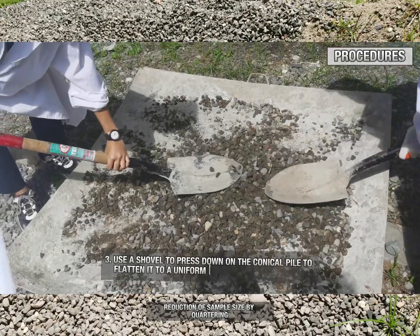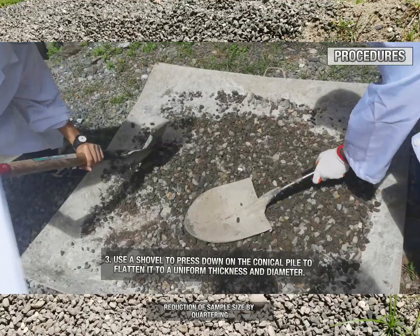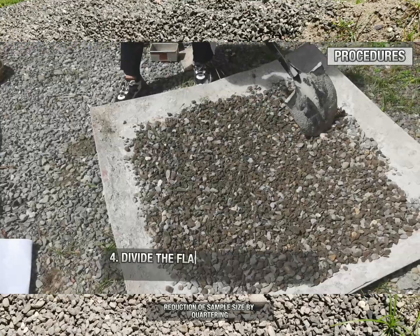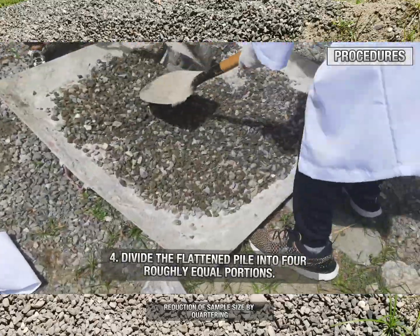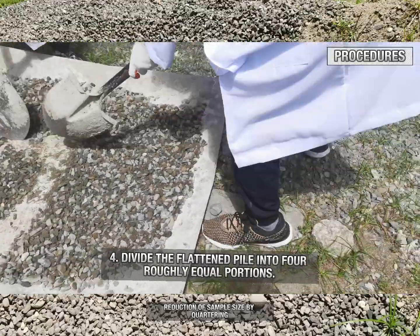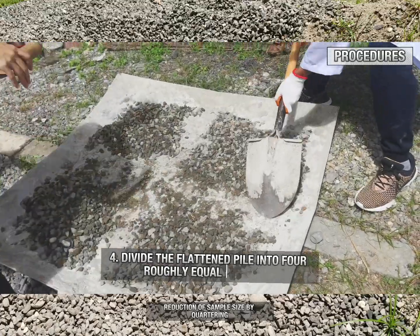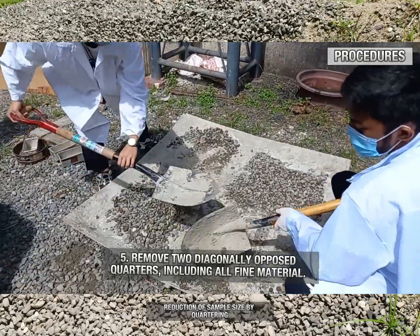Use a shovel to press down on the conical pile to flatten it to a uniform thickness and diameter. Divide the flattened pile into 4 roughly equal portions. Remove 2 diagonally opposed quarters, including all fine material.